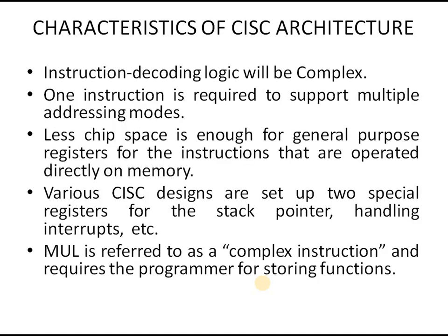Now just concentrate on the characteristics of CISC architecture. Instruction decoding logic will be complex. One instruction is required to support multiple addressing modes. Less chip space is enough for general purpose registers for the instructions that operate directly on memory. Various CISC designs set up two special registers for the stack pointer and handling interrupts.